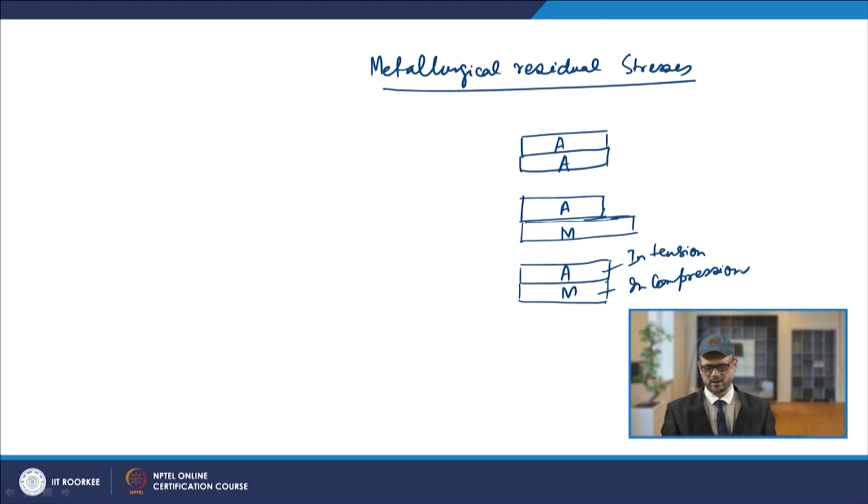So high compressive stresses are developed, with the surrounding constituents having lesser volume. You will have the development of these stresses, and that is why the stresses generated in these cases come under the category of metallurgical stresses.